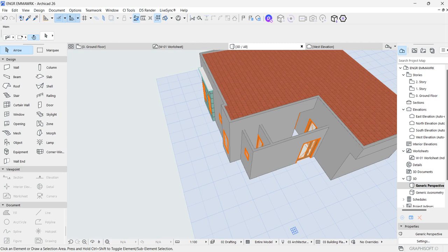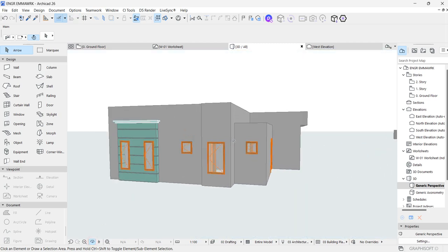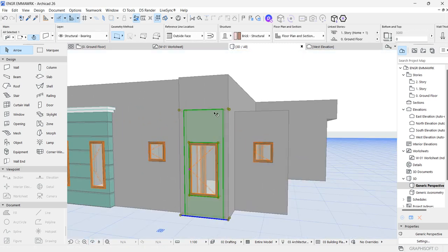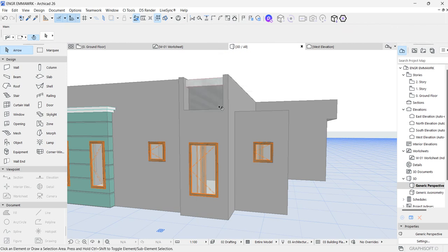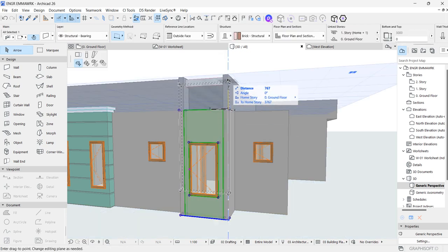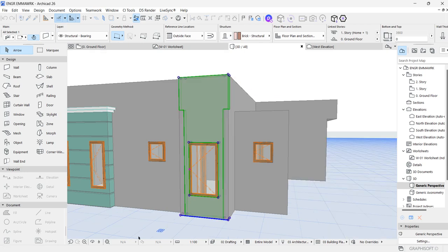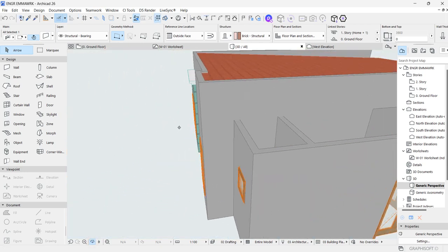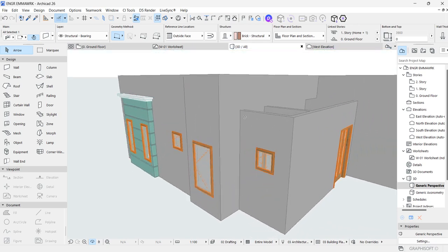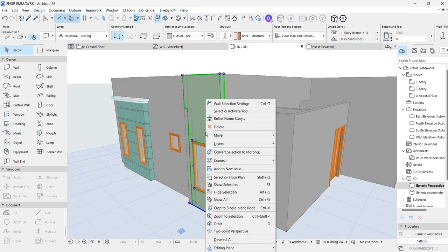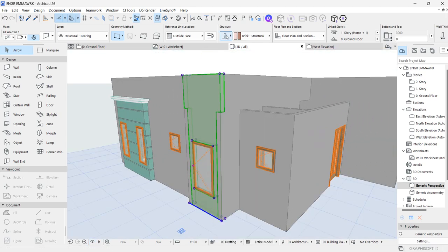If we're not going to use log detail, we're going to use complex profile. We're going to have a challenge with the height. So let's make all the heights the same, and I don't think we should cut it. Okay, so I'm going to convert this to composite wall, then edit.